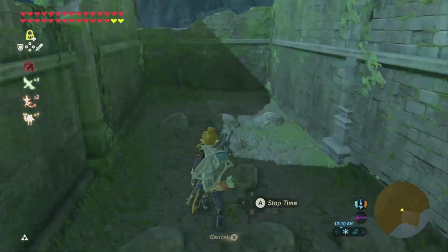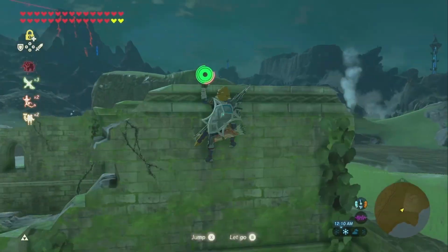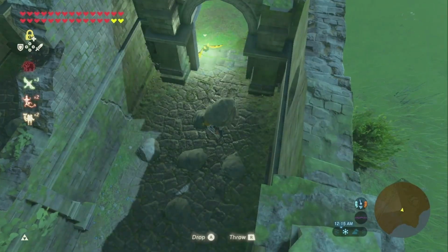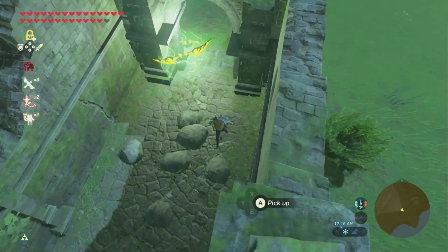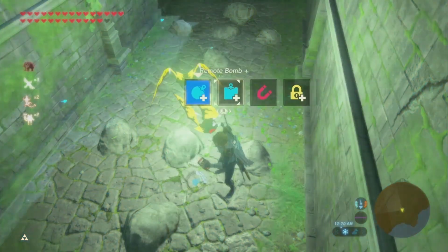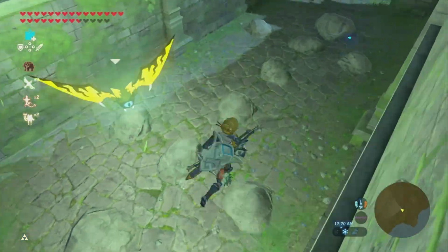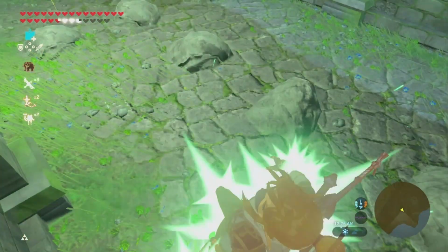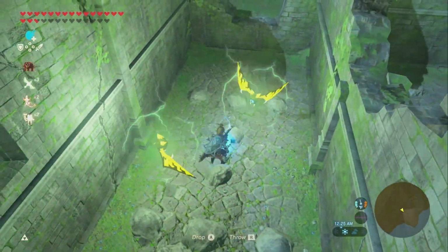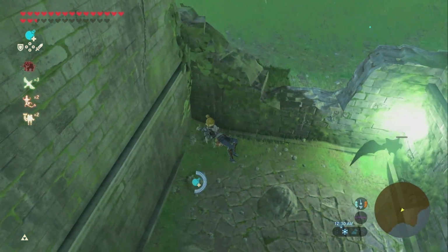its function. Strategy. When you remove the cover and move the flame rollout shield, make sure that both are intact and in good condition. If you see rust on either of these, you might suspect rust on the burner and combustion chamber. You must look more closely.